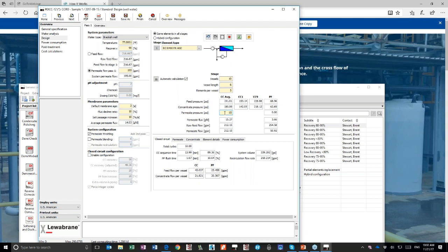See permeate throttling there, you clicked it, and what happens is the cell becomes cream colored as opposed to grayed out. And that allows you to, once you click permeate throttling, put a pressure into that line, and that will impact the feed pressure of the overall system, and it is representative of a height dimension in an overall actual field condition. I hope that's a satisfactory answer. Tricky one. Thank you, Alan.